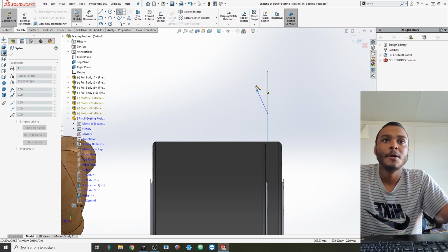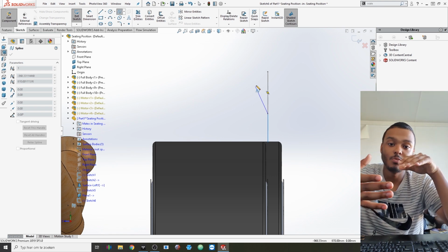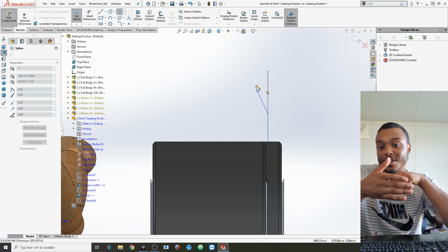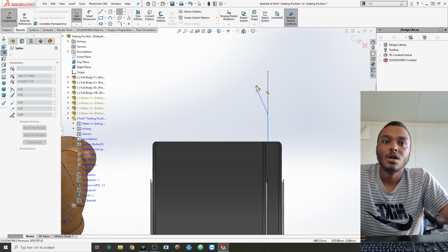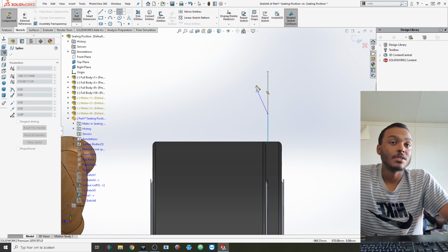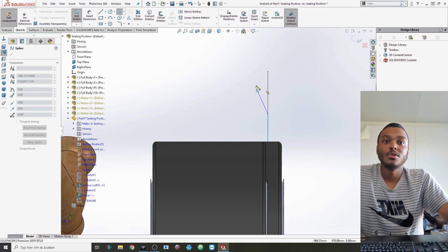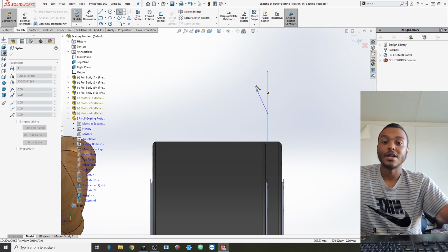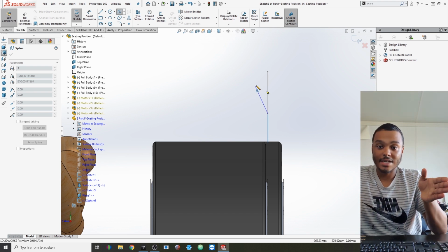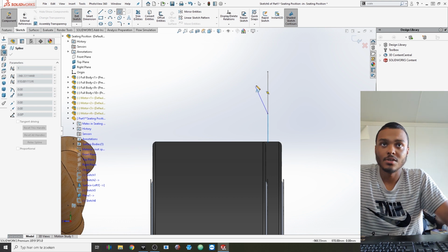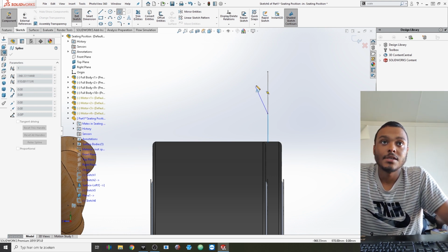So we don't need to do this very much to get the biggest fender that we can get, because we also want to keep everything as small as possible, because all of this will be frontal surface area that we need to push through the air, move it out the way and stuff like that. So we want to keep everything as low as possible with all of these fenders, but we still also need to make sure that we have enough room in there for not only suspension travel, but also the turning motion of the wheel once it is at an angle. So we need to have a little bit of extra space in there for those cases.